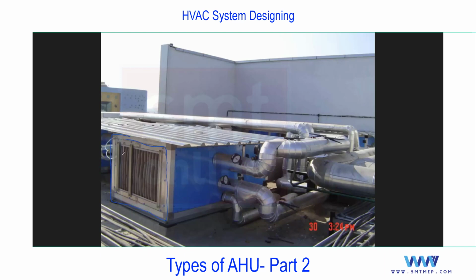The purpose of the sand trap louver is to what? Trap the sand, because in the Gulf area commonly you'll find sandstorms, no? If at the time of a sandstorm you do not use the sand trap louver, the complete filter will block. Okay, and what is a sand trap louver? We'll discuss at the time of air side. At this level, the sand trap louver is used to trap the sand at the suction side, which we are placing, which is connected to the FAHU.